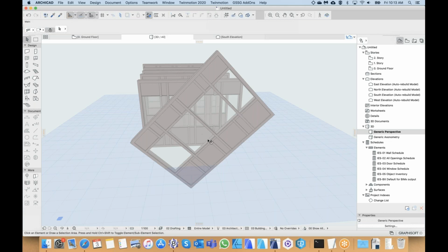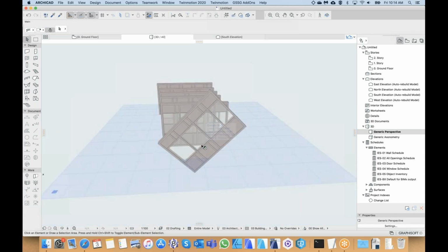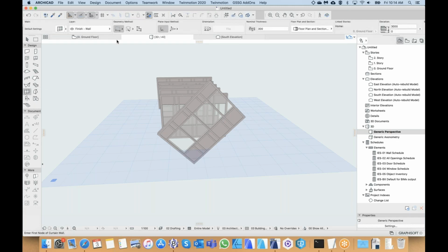We can also do this in, say, section elevation. We can actually draw a curtain wall, and we'll go through some editing functions in the section window a bit later. What I find handy is that we can rotate this down to the floor plan, and then it can be, for example, tiles on the floor or ceiling panels and stuff like that. Because we can rotate it in any direction, we can use it for pretty much any kind of grid-like structure.